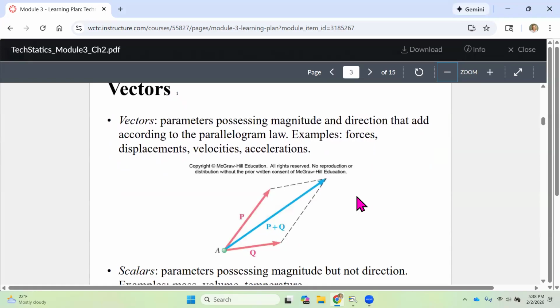Now, we're still going to be working with vectors, so it doesn't hurt to just remind ourselves a couple of things about vectors. Number 1, a vector is fully defined by both magnitude and direction. And a vector is not just a line, it's a line with an arrowhead. So when you're identifying forces, which we're going to be working with throughout, make sure that you always have an arrowhead, so that helps for us to determine what that direction is. Additionally to that arrowhead, we're also going to be adding angles when needed, okay?